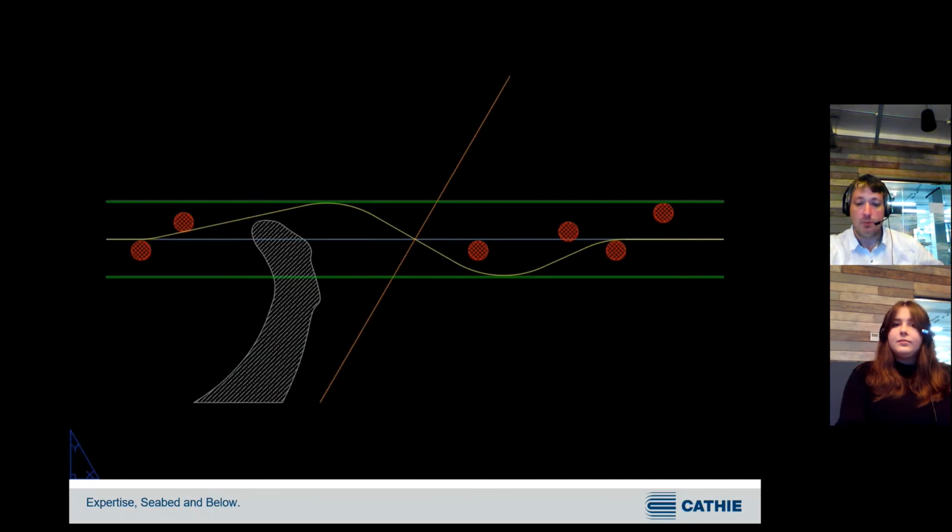Crossings are often the most complex part of a cable routing project. We tend to design these first, along with the cable ends, then fill in the gaps. Once the whole RPL is designed, we can export this to shapefile or geodatabase directly from AutoCAD Map. This can then be instantly used in GIS to calculate geometry attributes and check for clashes with constraints.